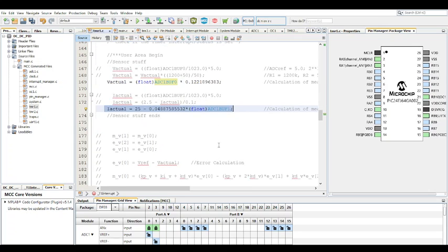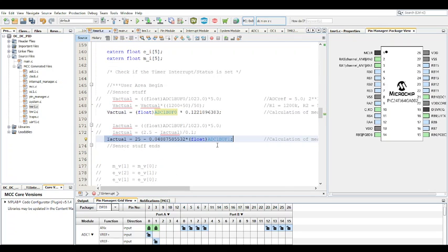This is the same across all microcontrollers. Obviously, with another microcontroller you would have a different register where you actually find it. I forget which one it is for STM, and I don't know which one it is for Texas, but you have to find out where they store it in the ADC. It's probably in some sort of buffer or register.